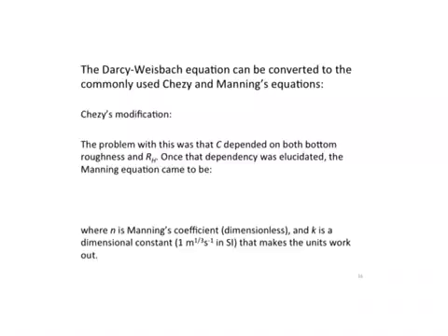So the Darcy-Weisbach equation is one of the 3 equations that's commonly used to predict velocity within a channel and to predict discharge. However, there are some other equations that are even more commonly used. There's the Chezy equation and the Manning equation. Now, the Chezy modification is that, if we were to solve Darcy-Weisbach's relationship, we would end up with U equals the square root of 8g times the friction slope, which is often approximated as the bed slope, assuming uniform conditions,